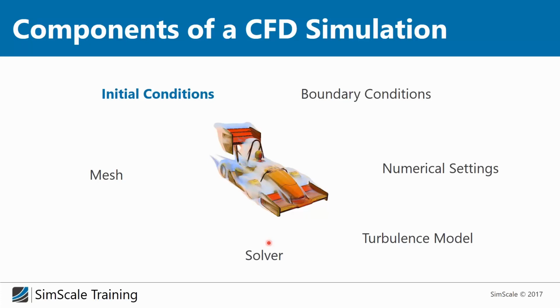Let's talk about initial and boundary conditions. As you remember, at the beginning of the presentation I showed you this last step of the CFD process, where our partial differential equations are transformed into a linear equation system which is solved. And for solving this linear equation system, or for solving differential equations in general, you need boundary and initial conditions.